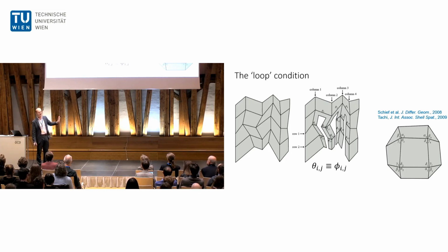It's very easy to show that by cutting all the facets, if you change one angle, you'll change all of the other angles. And the question we then have to answer is, how can you make sure that the pattern is such that the deformation you produce gives all of the facets in such a way that they can be joined back together again?